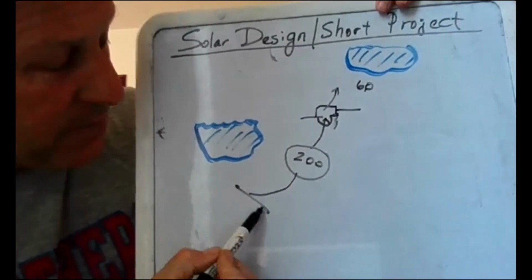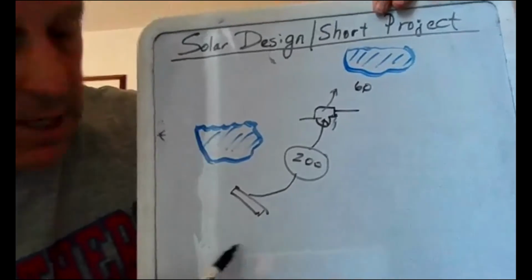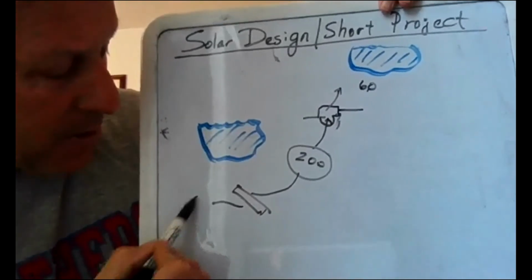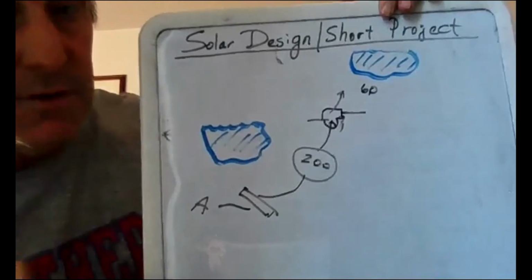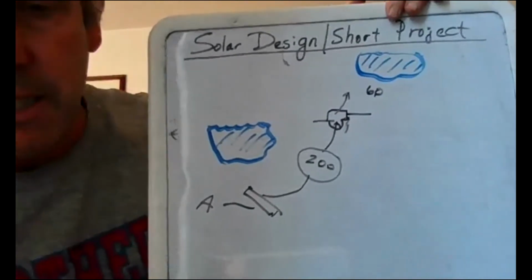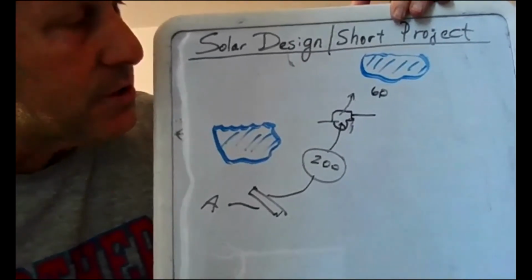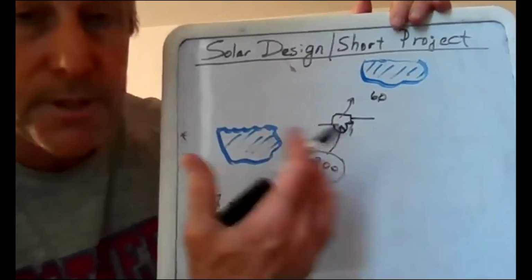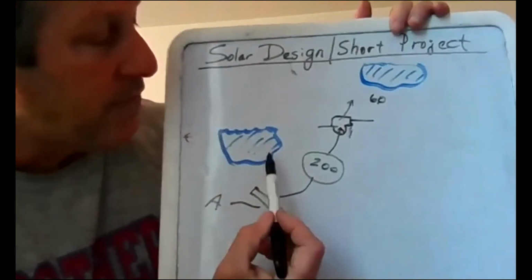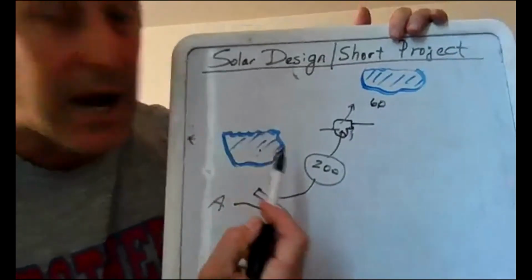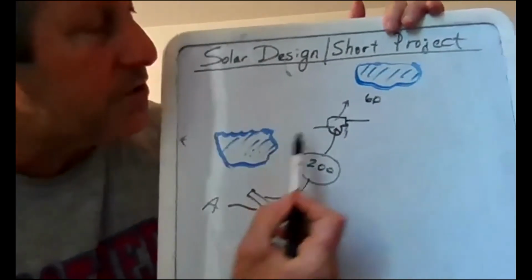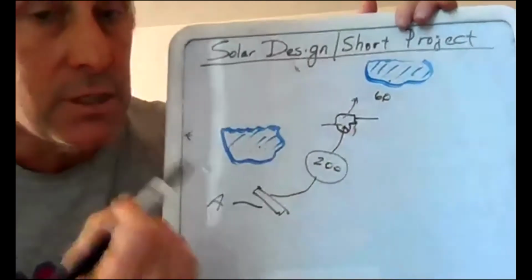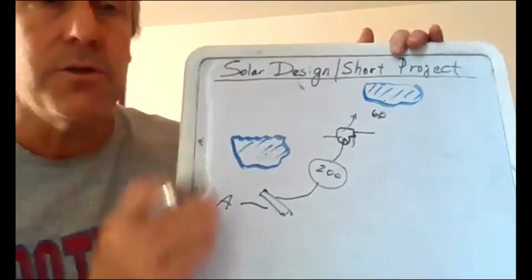That's going to come from my PV panel. Then I could work backwards and come up with the area of my PV panel, given the tilt and the azimuth I choose, et cetera. I could put together a complete system saying, here's this pump, here's this panel. If our job requirement is to take, say, 1,000 gallons, and over the course of a certain day, like May 1st, use solar energy to get it up there, you could complete that design.